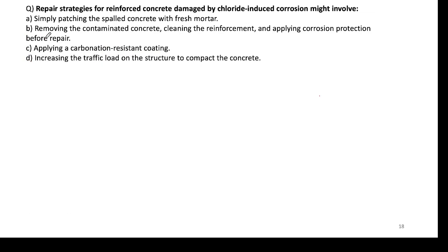Okay. Repair strategies for reinforced concrete damaged by chloride induced corrosion might involve. What are the different steps involved in the repair of reinforced concrete structures which are affected by chloride induced corrosion? Let's see. Simple patching of the small concrete with fresh mortar, that is one option. Removing the contaminated concrete, cleaning the reinforcement and applying the corrosion protection before repair.